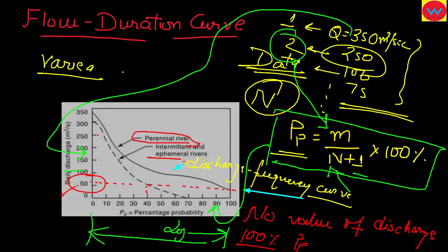The virgin flow duration curve, when plotted on log probability paper, plots as a straight line at least over the central region. From this property, the various coefficients expressing the variability of flow in a stream can be developed for description and comparison of different streams. For what we are seeing here, we will be looking through an example, a graph.